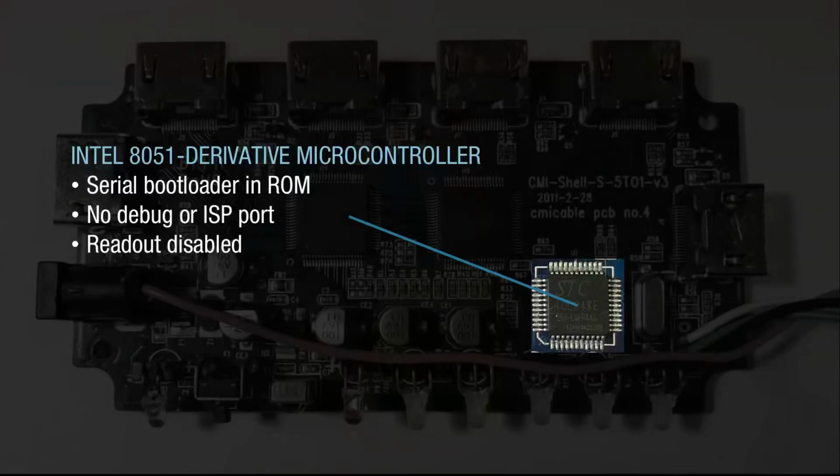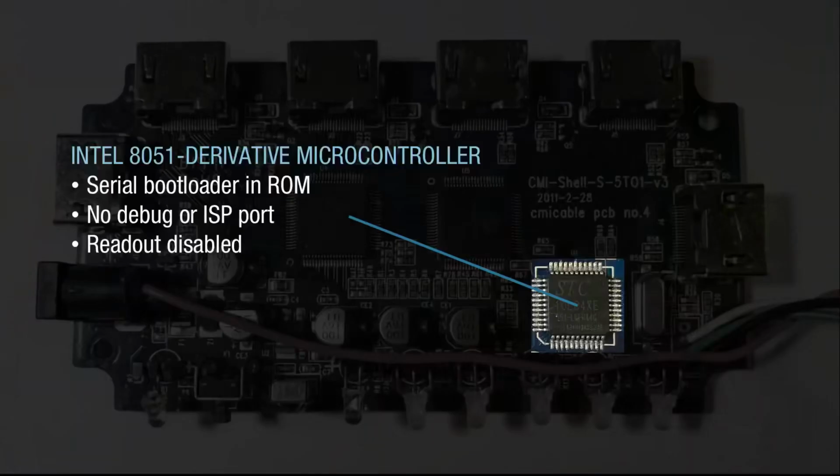And this device happens to be driven by an Intel 8051 equivalent microcontroller, a derivative microcontroller. And if I had the firmware for that microcontroller, it would have been probably 10 minutes of work to put a little bit of debouncing, a little bit of noise filtering into that system and be able to fix this and have this work. But without the firmware, you have to start off by rewriting the firmware from scratch, or coming up with some other hack, some analog filtering, in order to make this thing work. Or as I did, buy a slightly better HDMI switch.